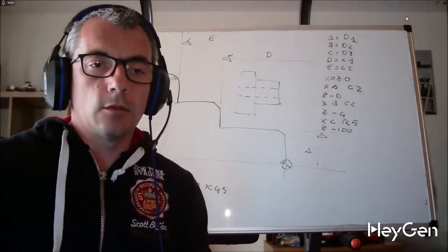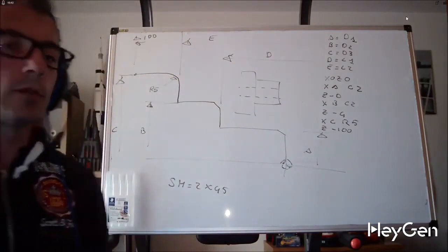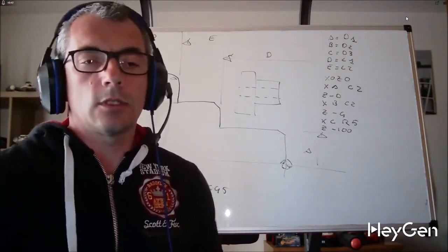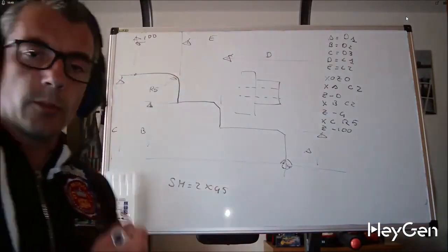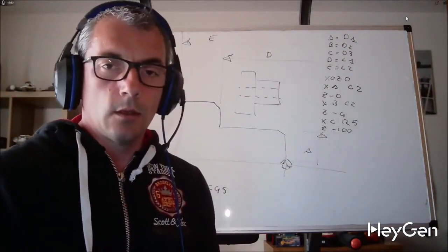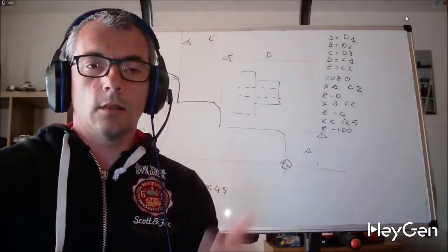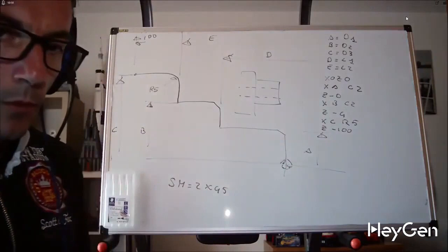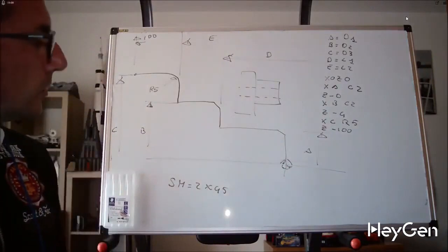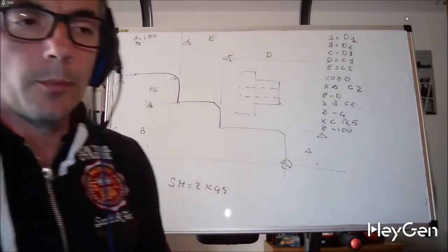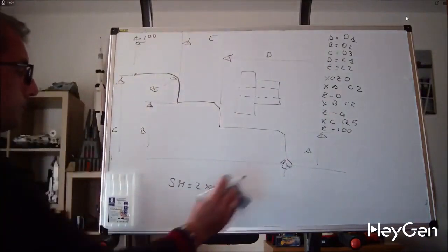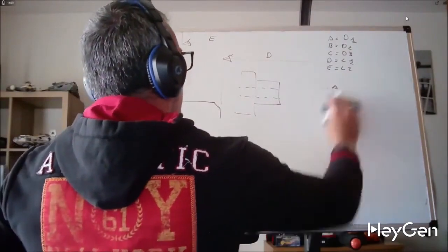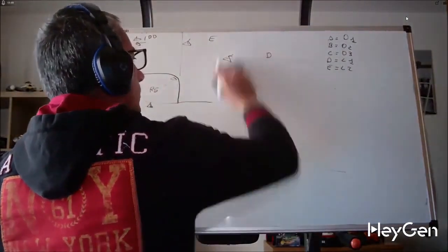With one program and 4 variables, I standardized all the pieces that this company needs to make, while also standardizing all the feeds, all the speeds and all the rotations, without having to force the operator every time to think, what data did I have in the previous program? Up, down, left, right. Just one program, 5 variables, managing 400 codes. At this point, I would do a practical example on the simulator, assuming I have a brush.